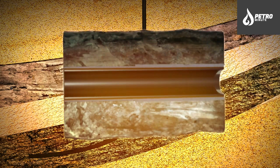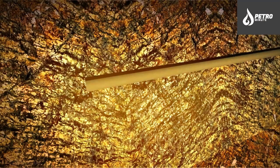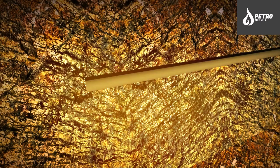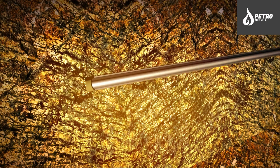Steel production casing is fitted and cement is pumped into the space between the casing and the borehole, called the annulus. This fixes the casing and prevents unwanted leaks from the well. With drilling finished and production casing in place, the well can be completed. This prepares the well for producing gas.